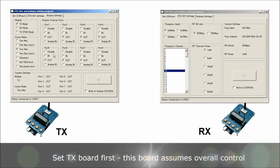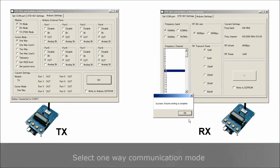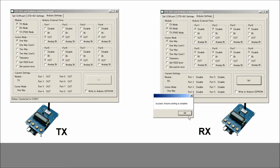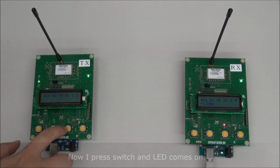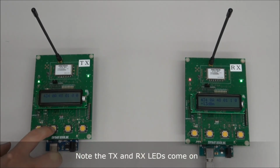So set the TX board first. This board assumes overall control. Select one-way communication mode. For the other board, you choose RX and select the same mode. Now I press the switch and the LED comes on. Note the TX and RX LEDs come on.